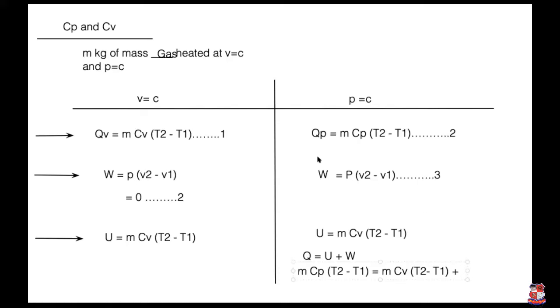If I write down the P V2 minus V1, in exam you can write down the P V2 minus V1. In the next step, write down the PV is equal to MRT according to combined gas law. So if M is common out, what is in a bracket? PV2 is MRT2, PV1 is MRT1. So M and R both are coming common out, and in bracket it is T2 minus T1.